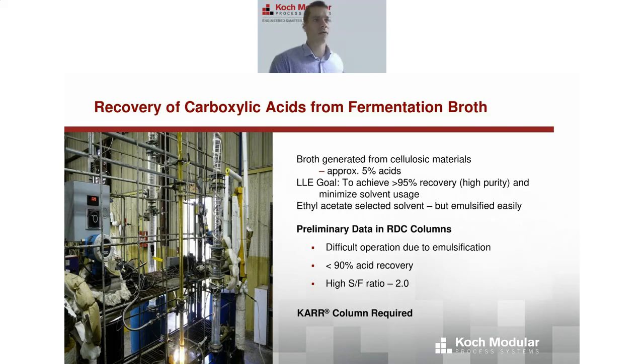And the goal was to recover 95% of those carboxylic acids from the feed stream. And the client that we were working with actually had done some of their own equilibrium test work. They identified ethyl acetate as an ideal solvent, but they found that it emulsified really easily. And they actually tried running a pilot test themselves using a type of extraction technology called a rotating disc column.